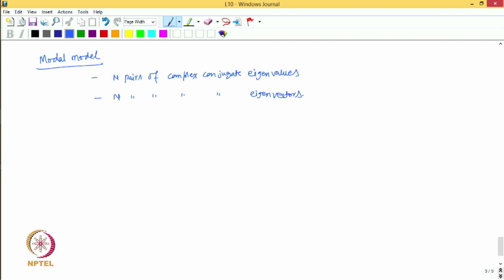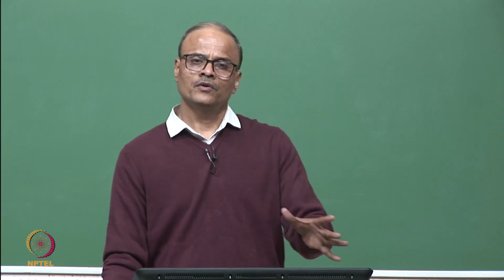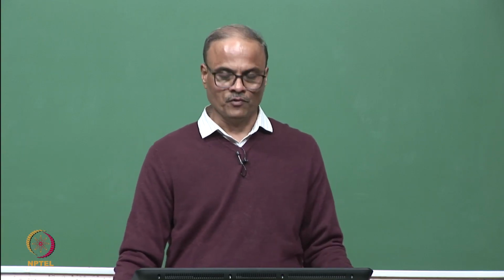So, each pair of complex conjugate eigenvalue and eigenvector together define one real mode of vibration of a multi-degree of freedom system with viscous damping, non-proportional viscous damping.